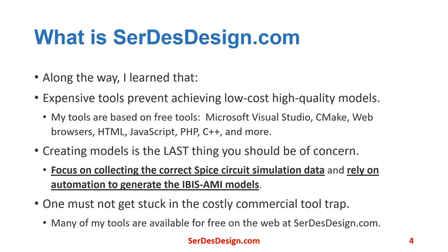Along the way, I learned that expensive tools kill all chances you have of achieving low-cost, high-quality IBIS-AMI models. My tools are based on free tools, Microsoft Visual Studio, CMake, web browsers, HTML, and more. I learned that creating an IBIS-AMI model should be the last thing you concern yourself with when it comes to creating IBIS-AMI models. Focus on collecting the correct circuit data and use automation. My tools rely on automation to generate models from measured and simulated circuit data.